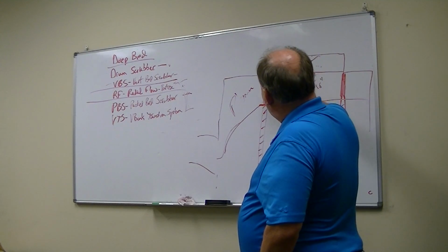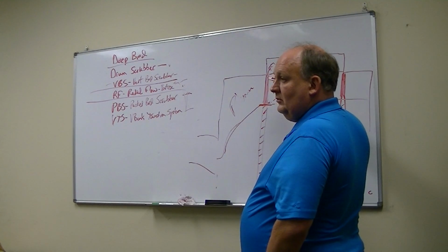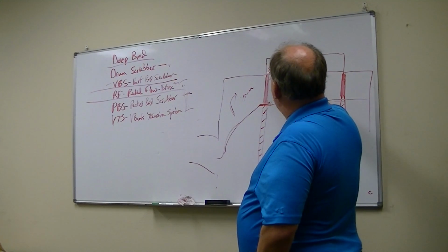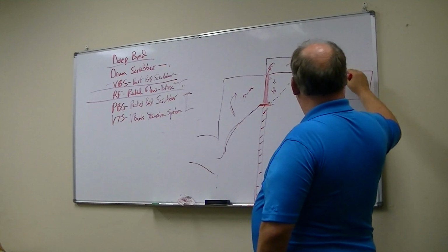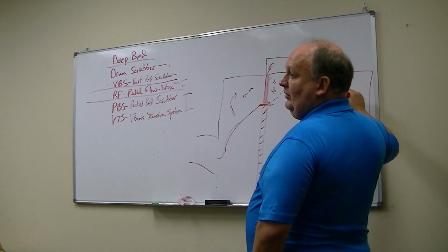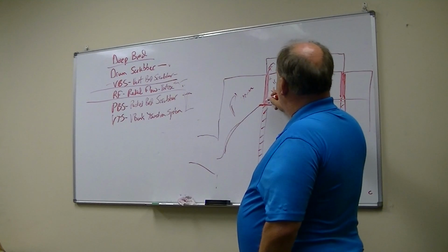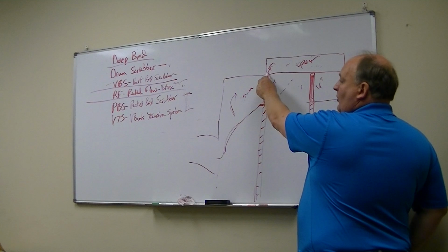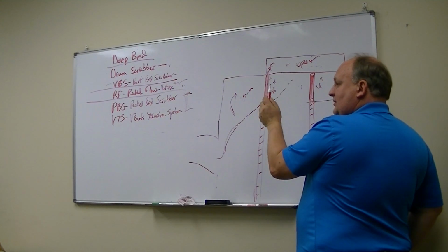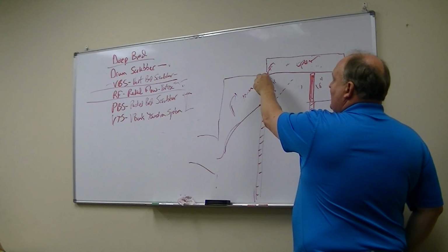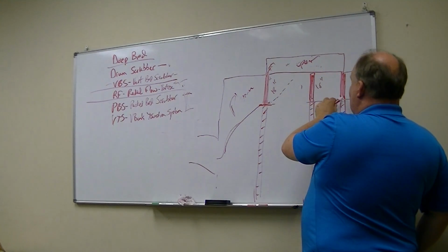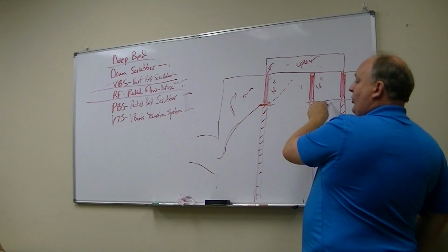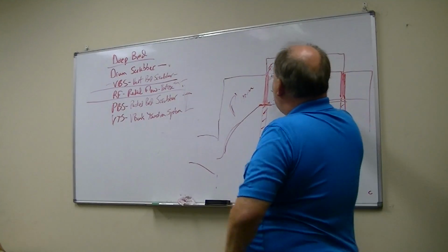well, some of it is first of all going to travel up the wall, because remember you've got 36 inches deep here, and this is only 18 inches, and then this is only 18 inches, so it's kind of the same route. Some of it is actually going to be a quicker route because the pressure drop right along the wall here is a little bit less. So you're going to travel this 18 inches and then this 18 inches a little bit faster, a little bit easier than you're going to travel the whole 36 inches, okay? So you get some leaking there.